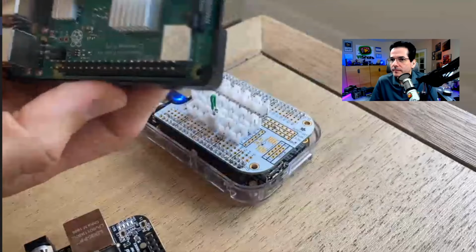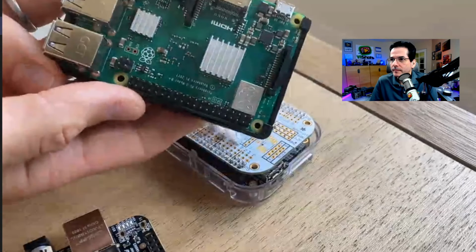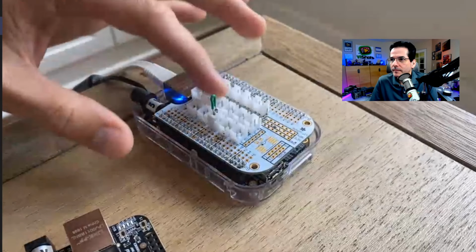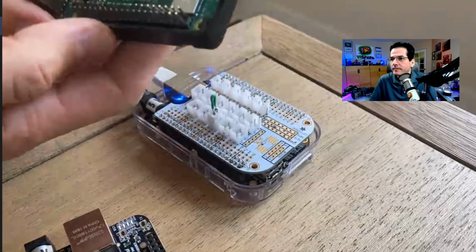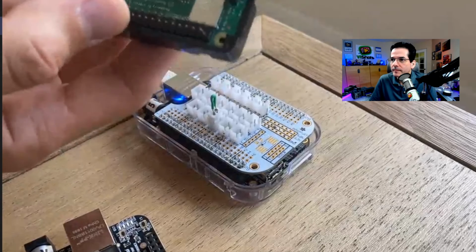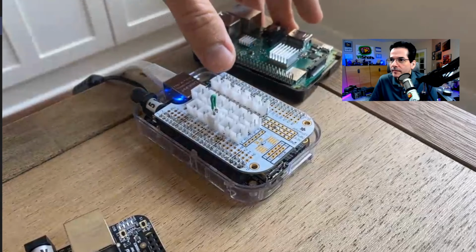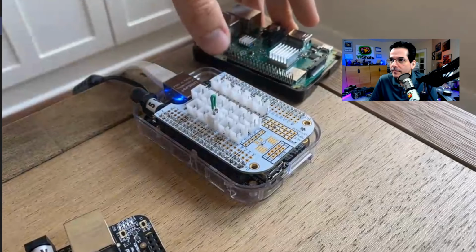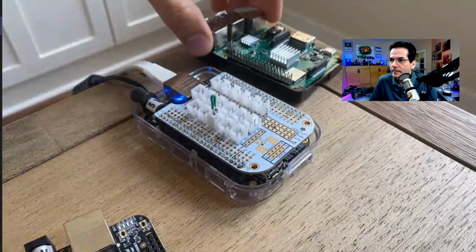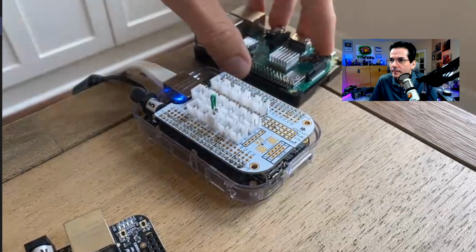And so I think it's just a matter of density of I/O for my purposes, where if I wanted 16 zones, I needed 16 digital lines. I don't remember exactly the number on here. I also think if you want analog input, that's built into the BeagleBone Black, whereas you would need to get some sort of daughter board with an ADC for the Raspberry Pi.